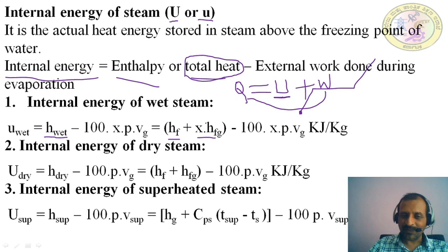Wherever you are using the steam as a working fluid, thermodynamic calculations are required. So how to make these thermodynamic calculations? Again you need all these properties of the steam. Enthalpy, entropy, these are all properties of the steam. Right? These properties of the steam are required at a particular temperature and pressure, that is the saturation temperature and constant pressure. These two are very important. Then the absolute pressure, I am showing here in the steam table. This is the temperature, which means the saturation temperature. This saturation temperature varies when you vary the pressure, so for different pressures you will get different saturation temperatures.